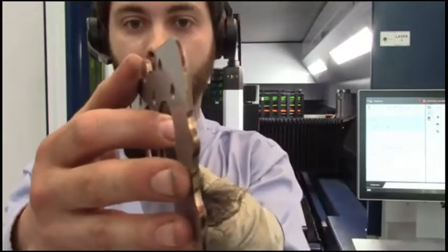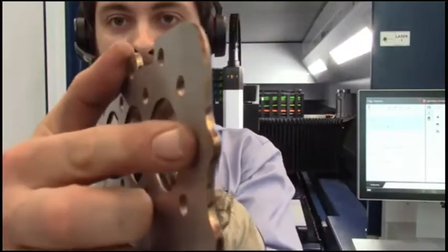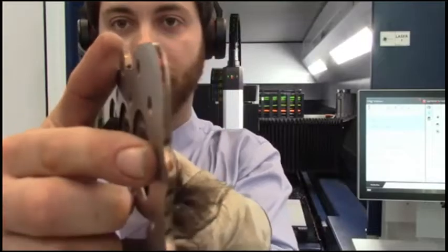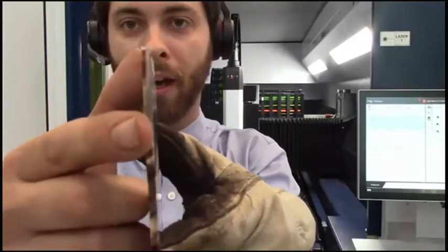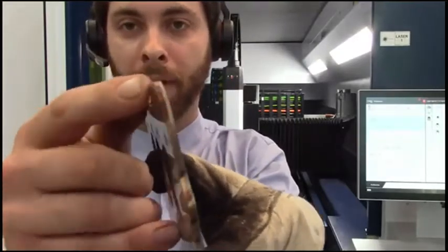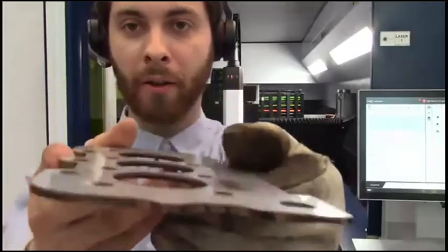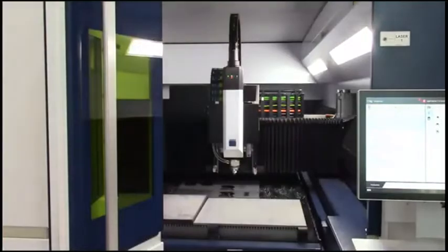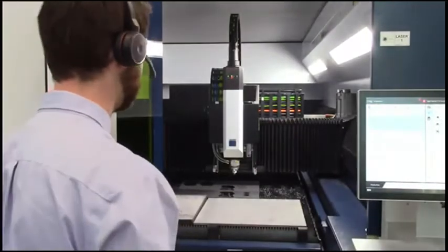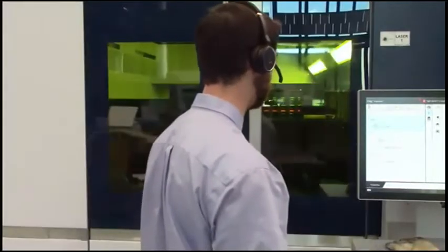You can see the side edge there. This is the underside of the part here. So if I can get it in close, you can see it's burr-free. It's got that oxidized edge that Brett was talking about before. So it is a little brown. It's not silver like the nitrogen cut. And to clarify too, at 120 thousandths, this is the maximum we can do without special nozzles, right?